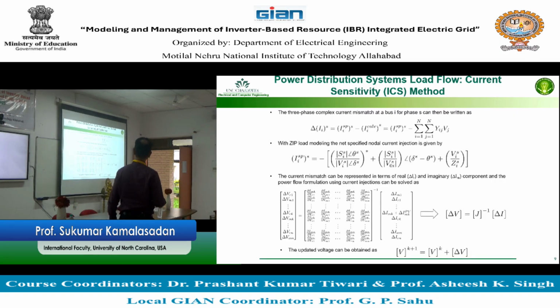How do you do the power flow using this algorithm? This power flow using this algorithm is not that bad. It sounds a little bad, but it's not that difficult. I'll tell you what it does. It actually looks at the current mismatch at every point. Current mismatch at every point can be represented as power divided by voltage, plus V square over Z. So let us look at this. This power divided by voltage is exactly what you did in forward backward sweep. Remember that we said S load divided by V, 2400 angle 0. So it's exactly what is being done.